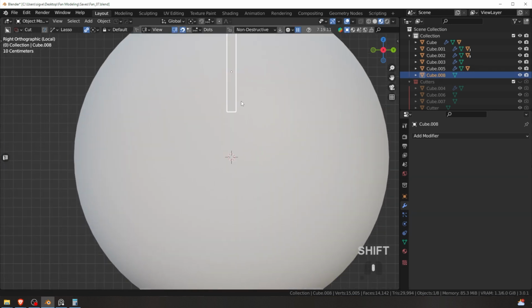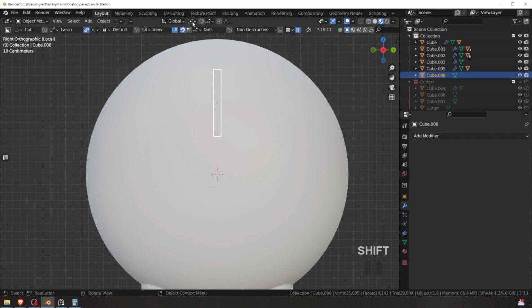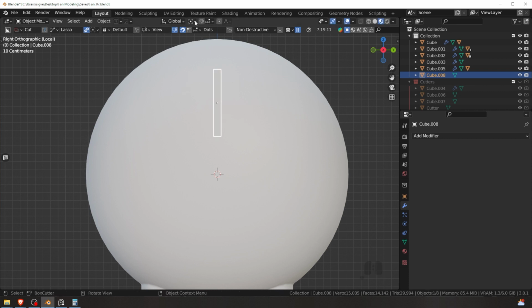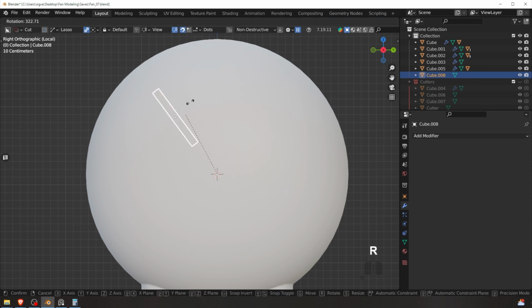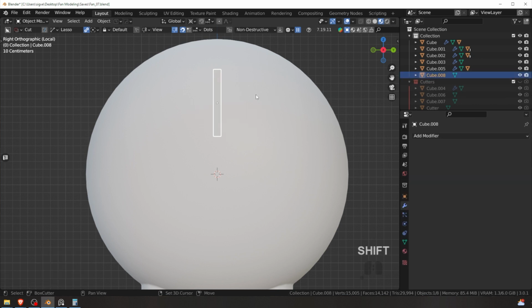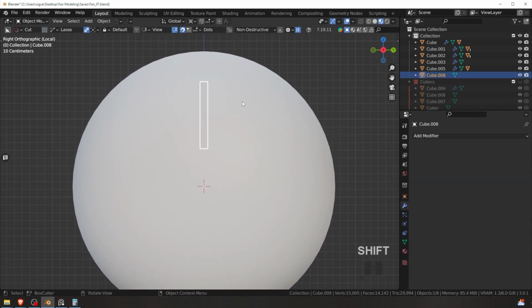And so now if we select this again, and before we rotate, we select this 3D cursor. If we do this, it's still not rotating around that, because we need to select here 3D cursor as the transform pivot point. And now it rotates around the whole thing like this. I mean, you could just go ahead and try Shift D and rotate, Shift D and rotate, but it's just too time consuming to do it that way.